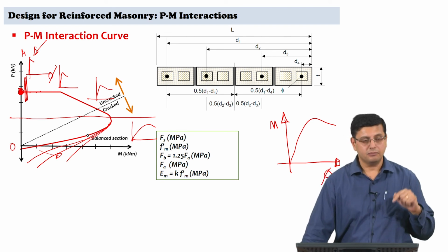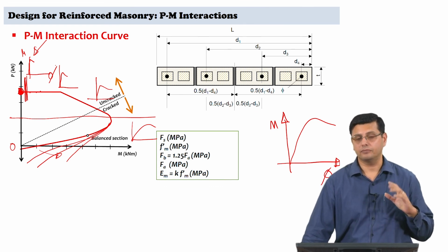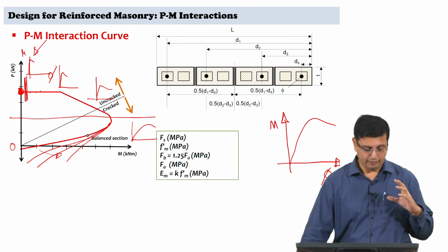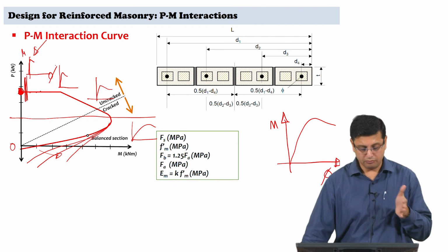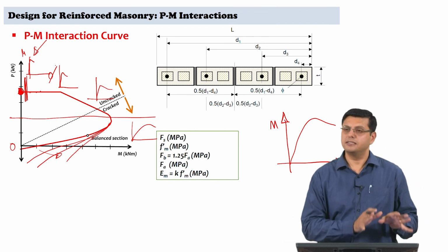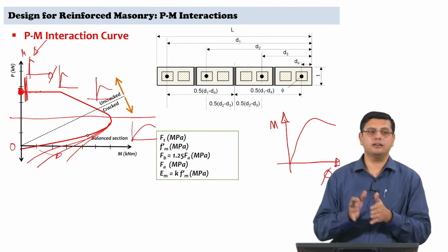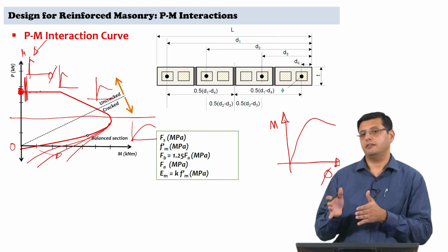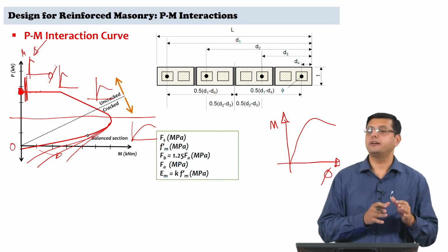So, masonry, reinforced masonry is an excellent choice for seismic solutions as far as providing good ductility, good deformation capacity in earthquakes. This single feature actually makes it a category that is far superior to moment resisting frames.